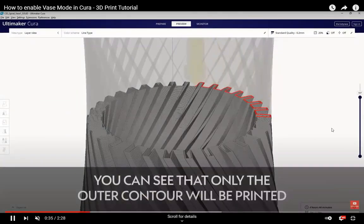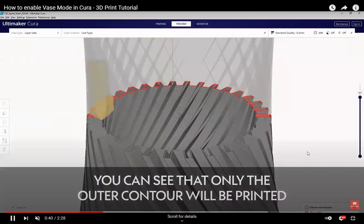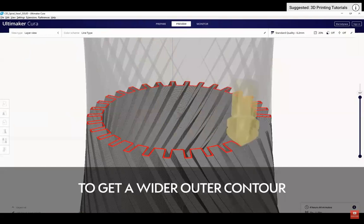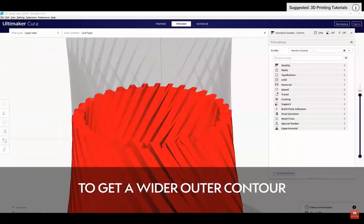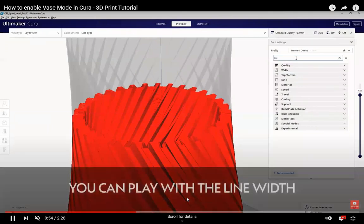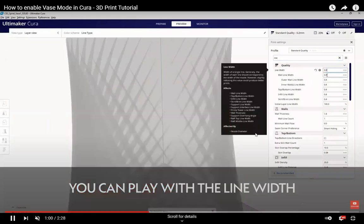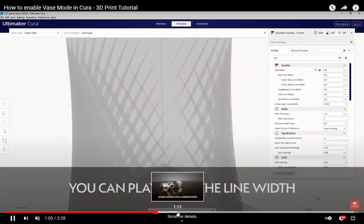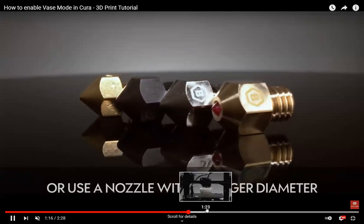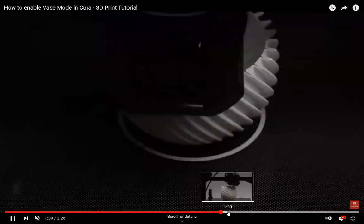And so this is how the Spiralize Outer Contour will build. To get a wider contour or to get a thicker outside shell, you can adjust the wall line width. And that's about it where they go to. They also talk about using different nozzles to extrude more material so you have a thicker build as well.